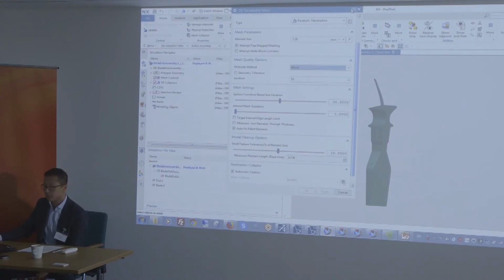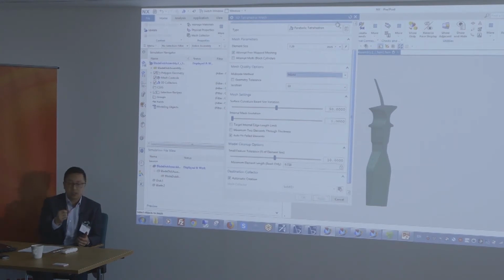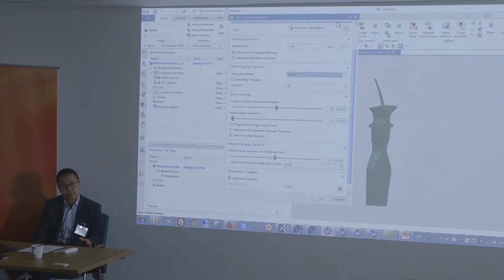Yeah, but I guess what I'm saying is, because what Volvo would accept as an acceptable shell mesh is not necessarily what Ford would or JLR. They've all got their own little flavours of what's a pass fail. So could you have a template for a JLR mesh, a Volvo mesh, a Ford mesh? As long as those criteria can be translated into, let's say, minimum mesh size, or quad angles, percentage of triangles and all that kind of stuff. Yeah, minimum Jacobian or maximum Jacobian, yeah. As long as those can be translated into functional requirements, we can have them in there.